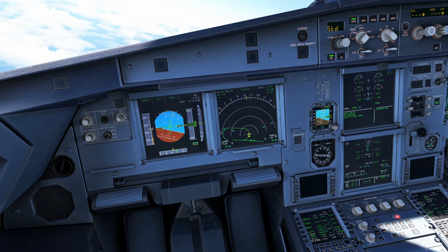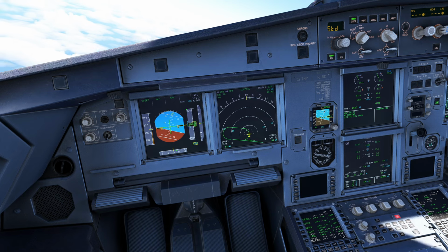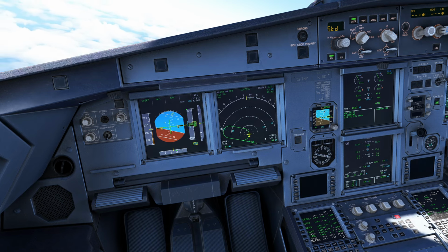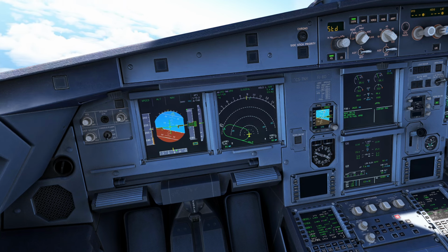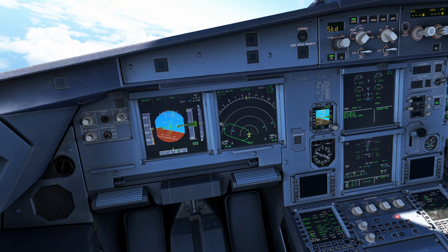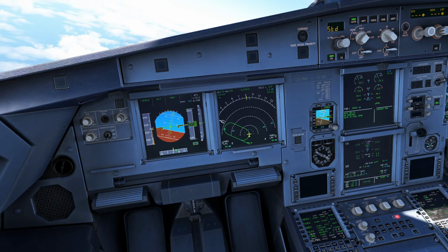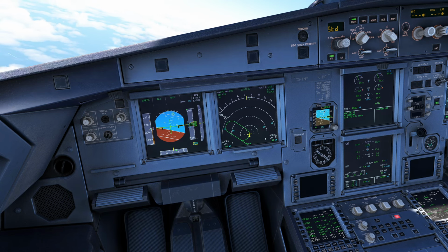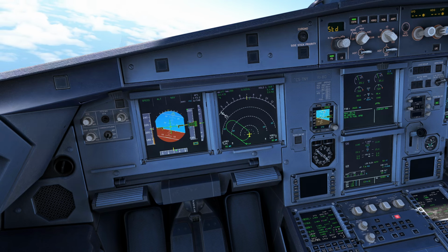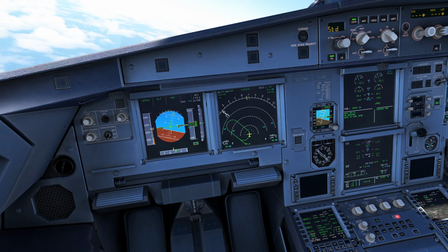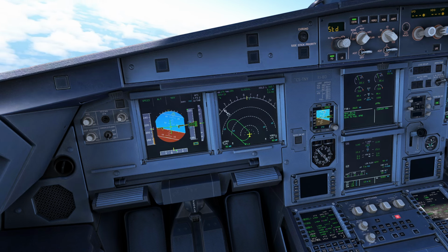You will be stabilized earlier and you can concentrate and focus on your approach around the aircraft, targeting the runway to find the active runway for landing, because you are free from configuring the aircraft and decelerating toward VAPP at the final stage of approach.